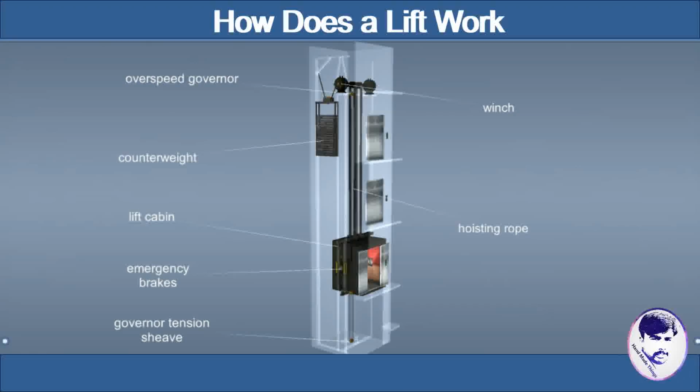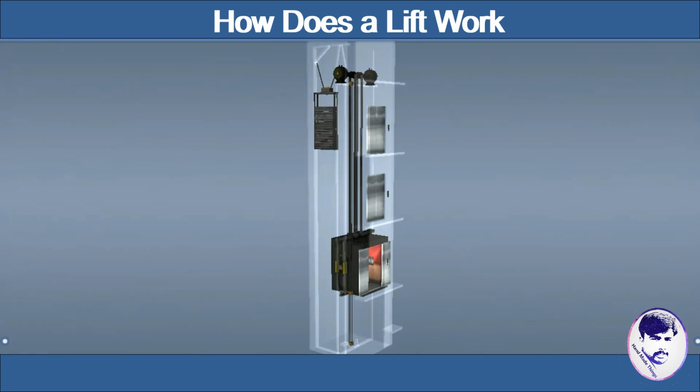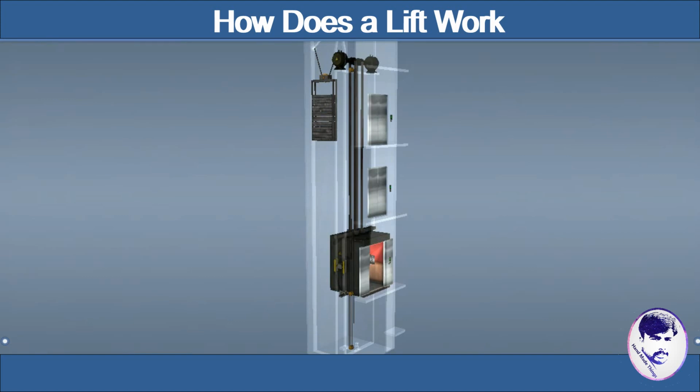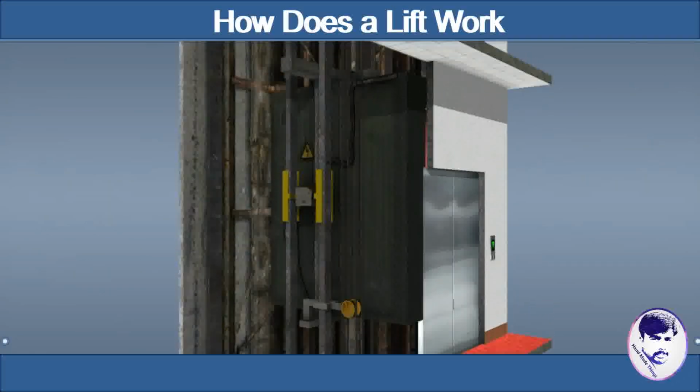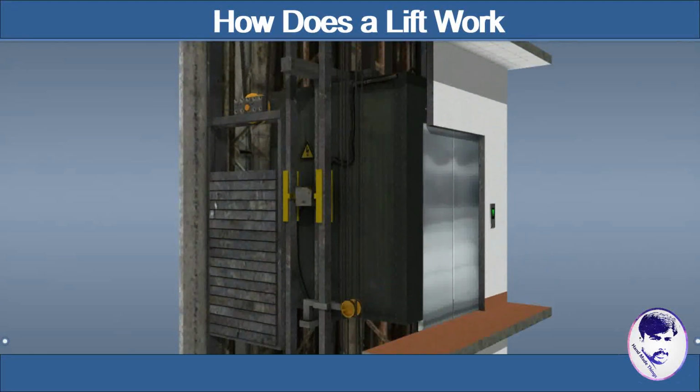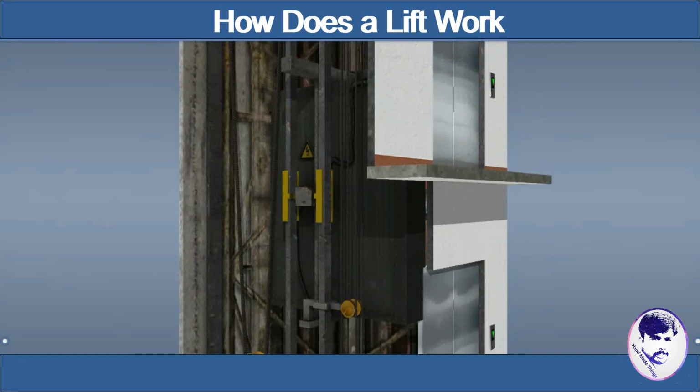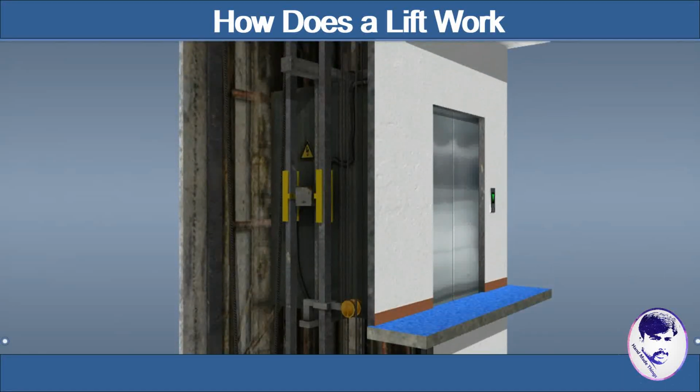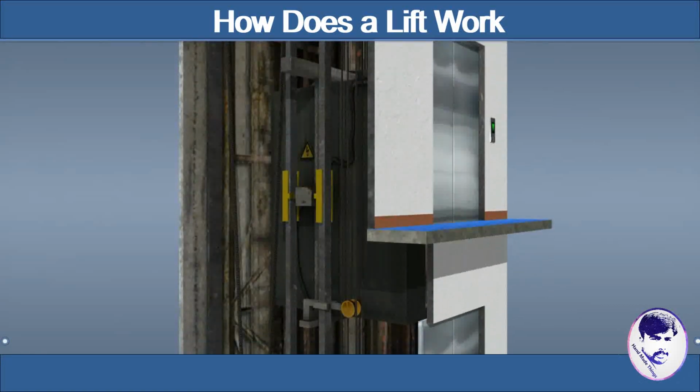The lift cabin and the counterweight in the lift shaft move between cabin guide rails, while the drive gear, the motor and the control unit are found in the engine room above the shaft. The type of control system of lifts depends on the height of the building. In the case of low-rise buildings, only a simple call button is used. In skyscrapers, however, when calling a lift, it is possible to enter which floor the person would like to go to. The control unit can then calculate which cabin is ideally positioned for the required journey.